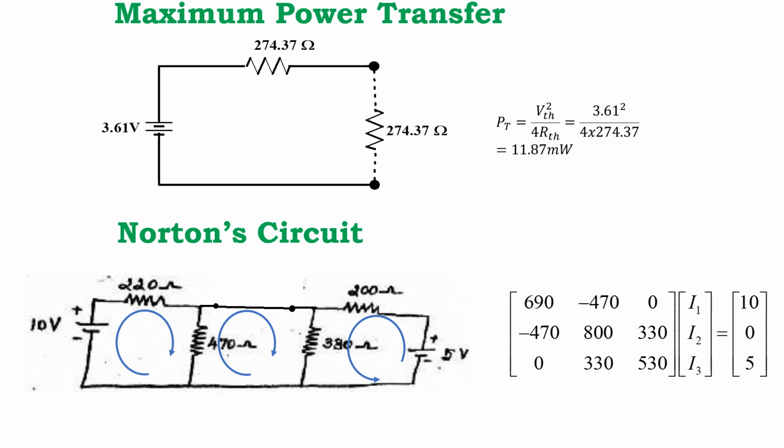With the same circuit I am starting the Norton theorem. As I mentioned, Norton theorem uses the short circuit current. So I removed the load and short circuited this point. You can see this point, this is the short circuited point. Once you short circuit, you can see it is a 3 loop circuit.